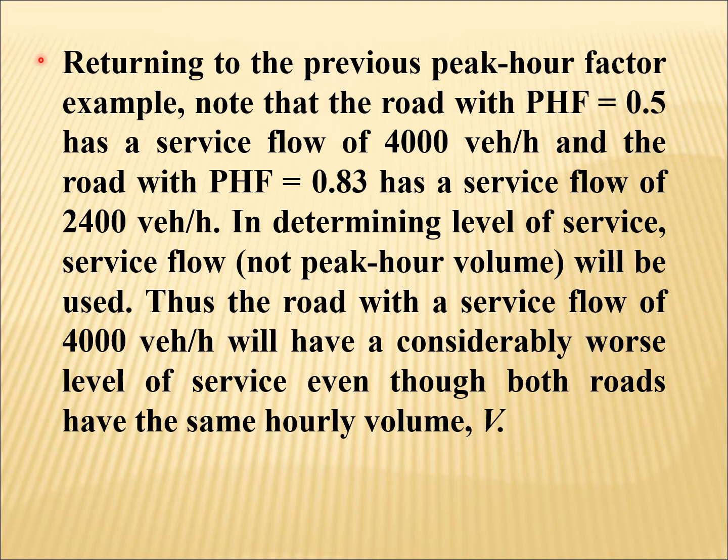Returning to the previous peak hour factor example, note that the road with PHF equal to 0.5 has a service flow of 4000 vehicles per hour, and the road with PHF equal to 0.83 has a service flow of 2400 vehicles per hour. Now I need your special attention in determining level of service. Service flow will be used, not the peak hour volume. So I will repeat that in determining the level of service, service flow will be considered.